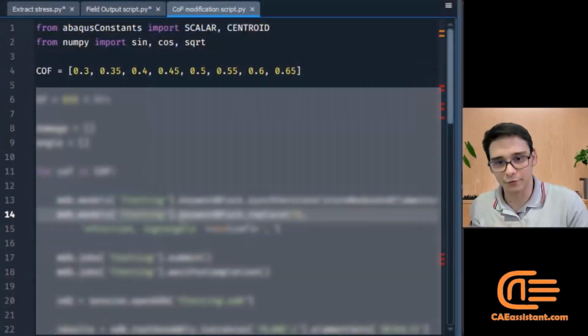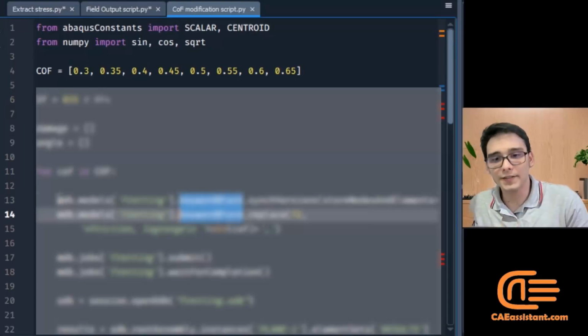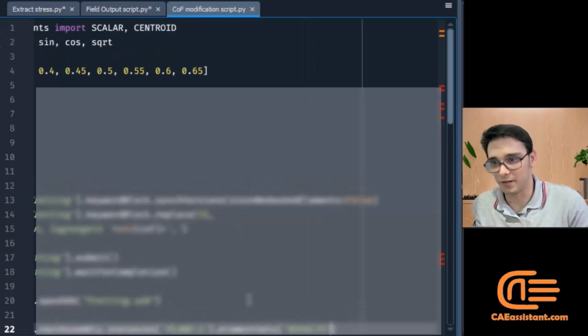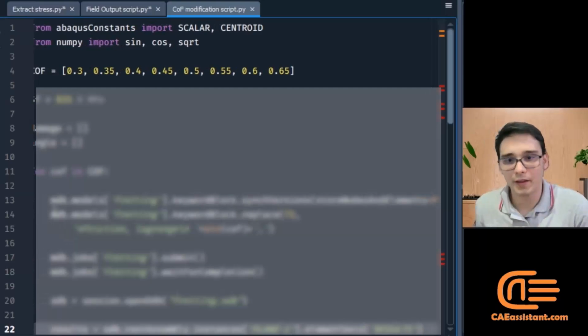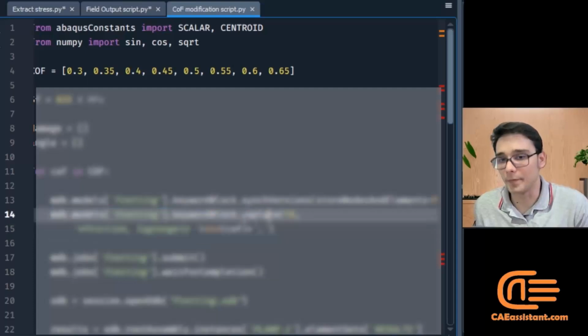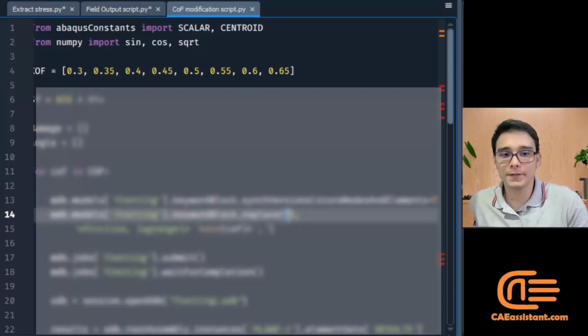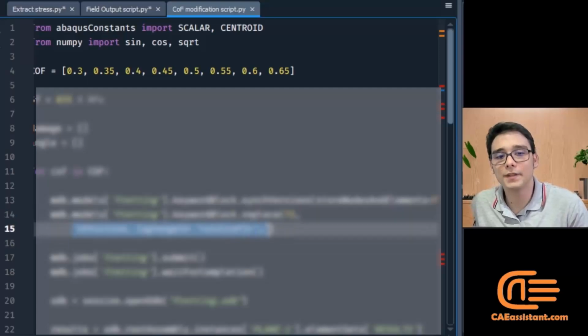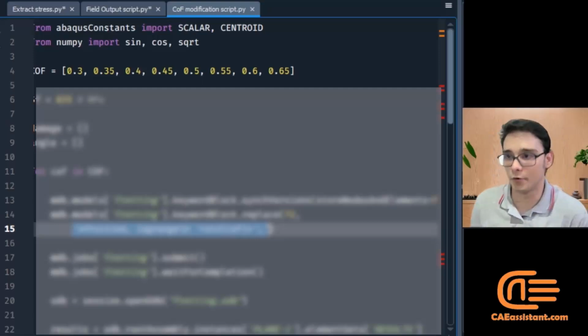I'm going to teach you something about this script prior to doing this. What this does is just take all the values of the nodes and elements in order to change them on the model. And then this other script part is the one to replace. As you can see here, it is a keyword block replace. The first argument of it is the line that you're going to replace. And the second argument is going to be the new value that you're going to replace it with.